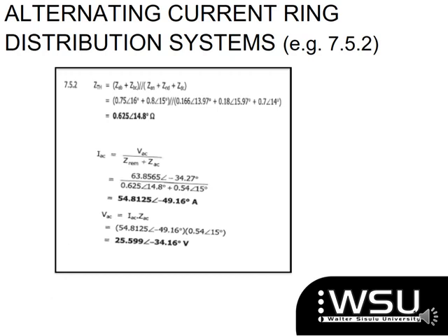So now we go to the second part of the question, where they ask for that same voltage drop, but they want to know when you have an interconnector in it. So when you have an interconnector in there, you go back and put that interconnector. You don't remove that equivalent circuit that you did already, all right? It still remains in that you've changed that delta scenario into a star scenario.